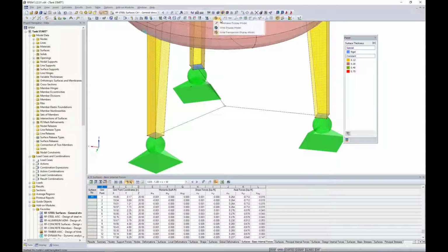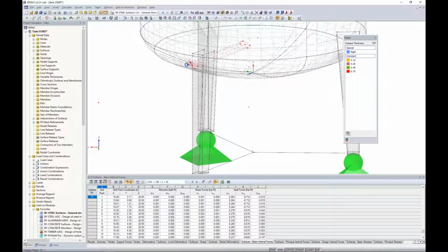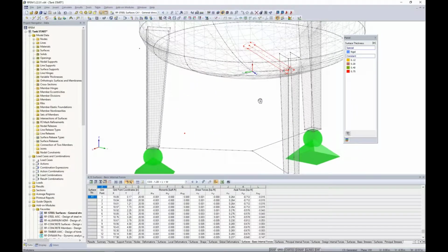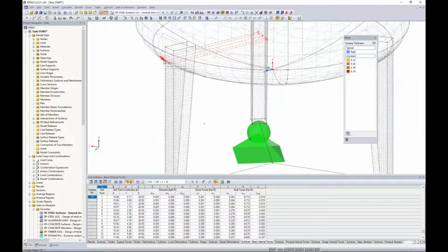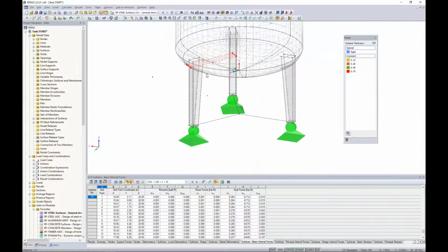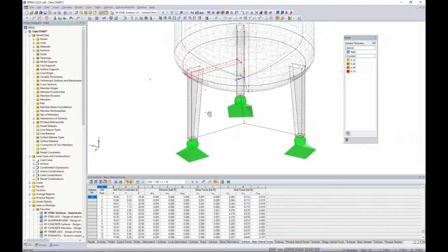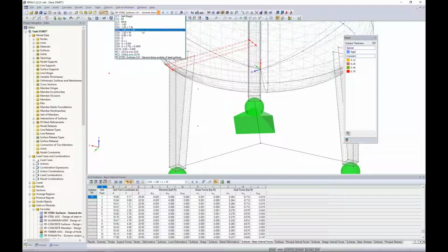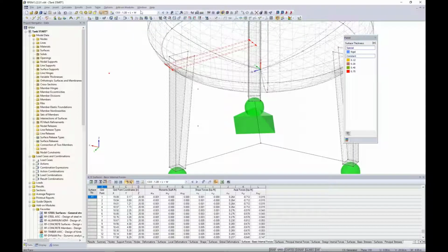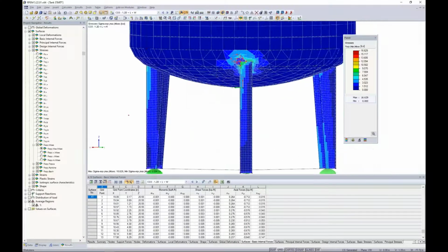We have an average region defined here. And I know it's a little bit difficult to see, but you can see that we've applied this 2-inch little average region. It's being projected towards the center of the tank structure. So when I apply this average region, I'm going to view my results for load combination 3, and we can turn these on. And I'm going to kind of maneuver my model here and zoom into this point.